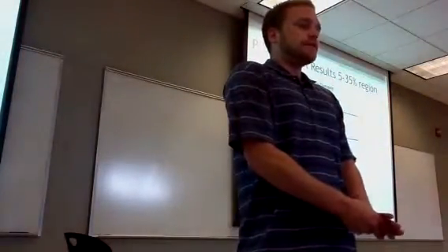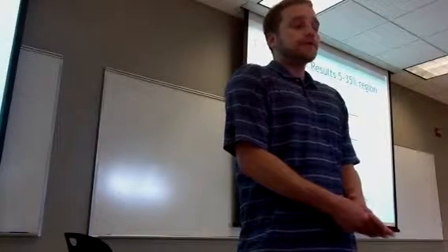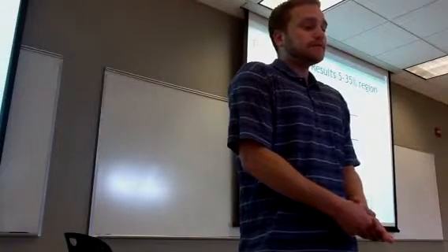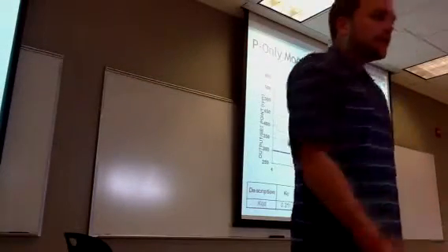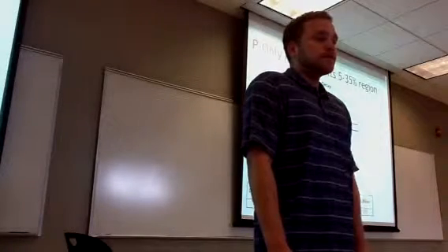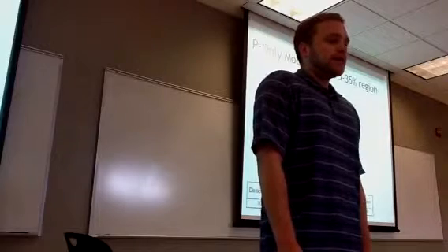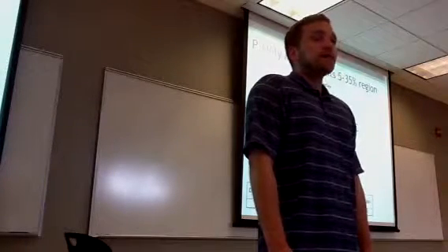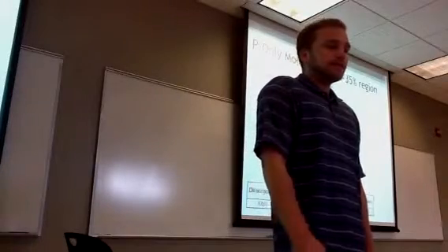Here's the P-only model results from the 5 to 35% region. This was critically damped and gave us a settling time of 0.3 seconds and an offset of 54. Here's the P-only model results with quarter decay, and quarter decay was at 0.311% per RPM for controller gain, and a decay ratio of 0.25 with a settling time of 0.5 seconds and an offset of 16 RPM.